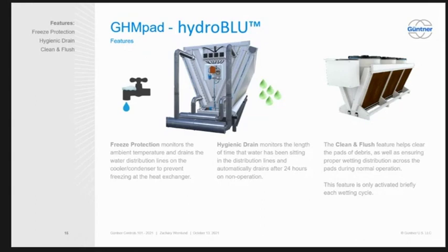Normally we don't use two Belimo actuators, one for the feed and one for the drain. Normally we have a drain solenoid right here, and now we got them back, so we're installing them. But during the shortage, since we couldn't get the drain solenoid, it was either hold up the unit and not ship it out, or figure something out. We had Belimo valves, so we repurposed them as a drain valve, and we had a little bit of a growing pain, and there were some times where they weren't set up properly.